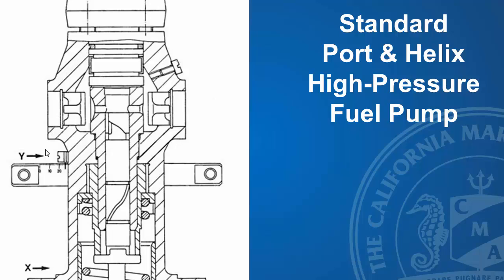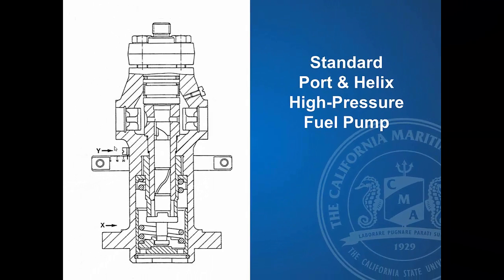That shock wave will hit the injector needle valve and snap it open very, very quickly, and that's what you want. So you want to accelerate that pump plunger as quickly as possible, and you want it accelerating strongly before the ports close, and then that will give you a good shock wave for that instantaneous opening of the injector. And that's very, very important to prevent particulates. You want a high pressure flow out of the injector nozzle to give you better atomization.